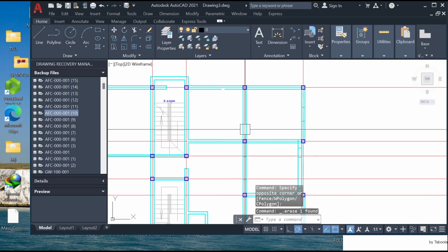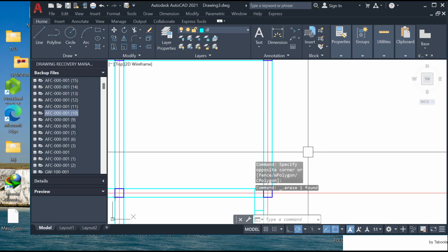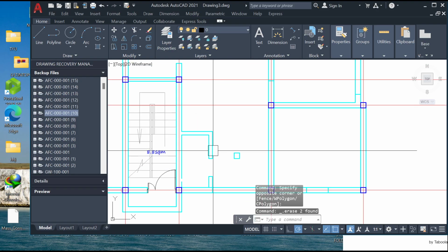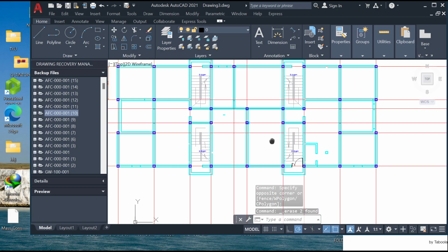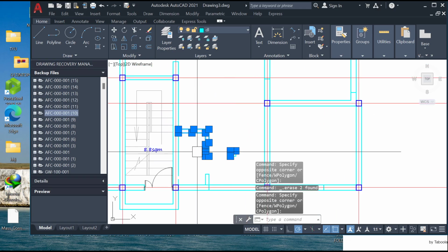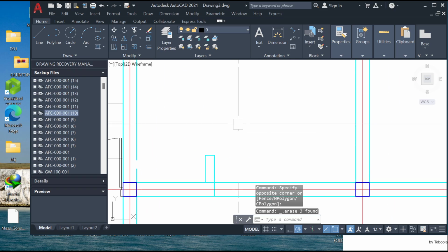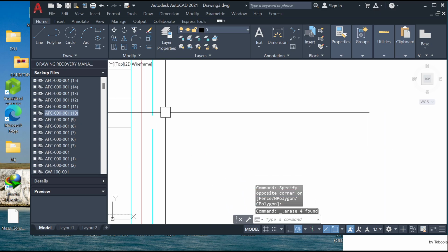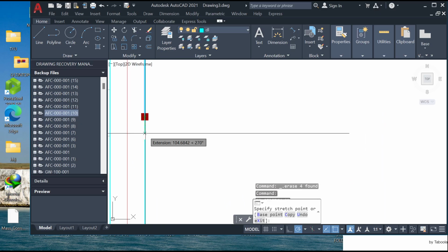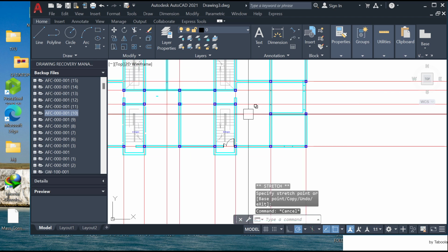Now let's delete this. Let's remove this. Very good. This was measured the other time, and we said it's 28 meters, so we can leave this. But after the analysis, if we see anything that we are not okay about, then we can increase the section or break the span.